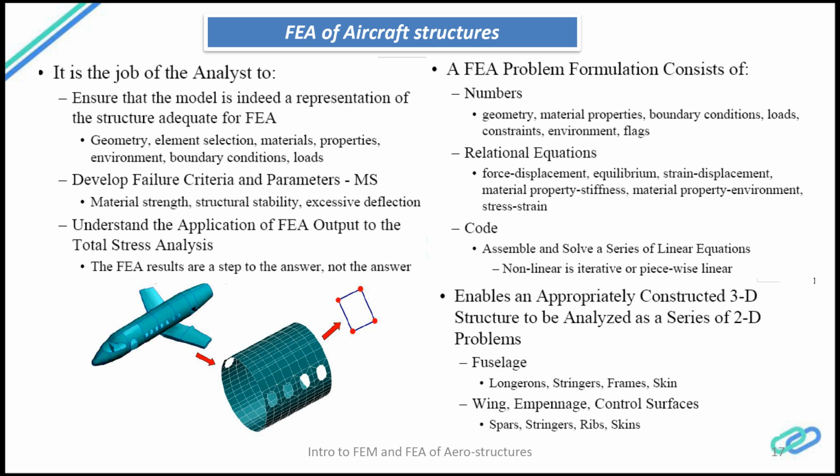The assumptions are what kind of boundary conditions to use, what kind of elements to use, how to idealize the structure very effectively, what kind of materials to use, and what kind of loads act on the structure, which should be accurately captured, or at least captured in a reasonably close sense in the model.